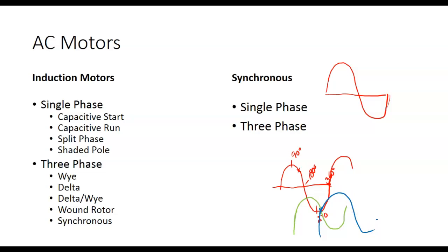So how much more power could we transmit? We got to use two wires anyway. How much power would we be able to transmit if I add that third wire? 70.7% more power by adding one more wire.